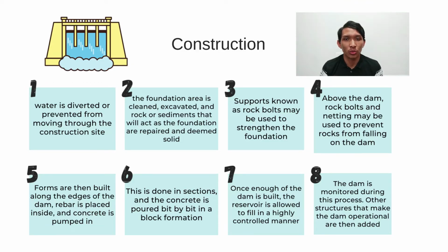Assalamualaikum warahmatullahi wabarakatuh. My name is Muhammad Adit bin Salim. So I will continue with the construction of the hydro dam. Firstly, before we start the construction, the water is diverted or prevented from moving through the construction site. The foundation area is cleaned and excavated of rocks or sediment that would weaken the foundation. Supports known as rock bolts may be used to strengthen the foundation. Above the dam, rock bolts and netting may be used to prevent rocks from falling on the dam.